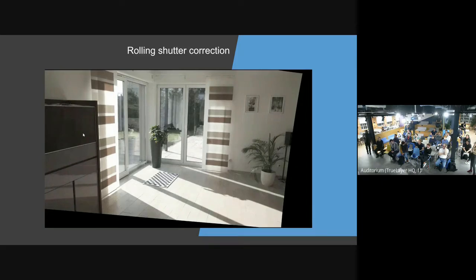It's just going from the full resolution top to bottom and uses like 4,000 different data sources for one frame. So it's really simple to implement once you understand how to counteract that, and it turned out to be working very well. So yeah, now we have all the stability, and the stabilization itself is really not that big of a deal. It's very simple. If you have the rotation from the gyro, you just apply that to the pixel and move it according to this rotation matrix. So the stabilization itself is pretty simple too. So we have all of that.